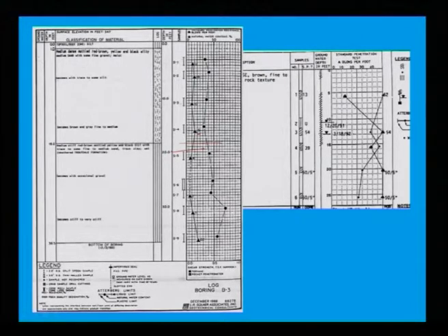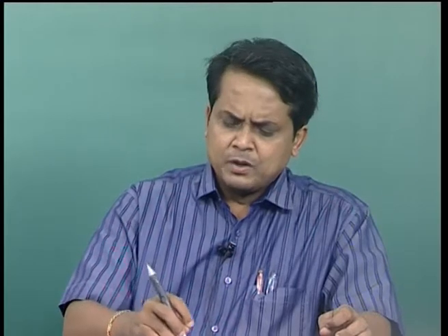Here it is varying, water content is say 48%, 47%, 46%, 45%, 46%, almost consistent. So, preparing a data logger this way is a better way to represent, and it will be very easy to extrapolate. If somebody can visualize at first instance, he can say how the penetration value varies, and based on the penetration value, what your strength value should be, that you can indirectly interpolate or extrapolate.